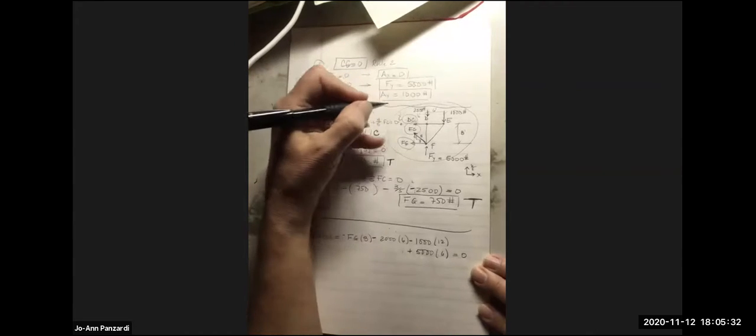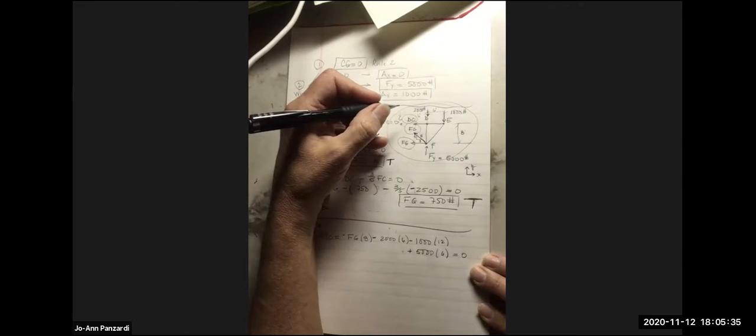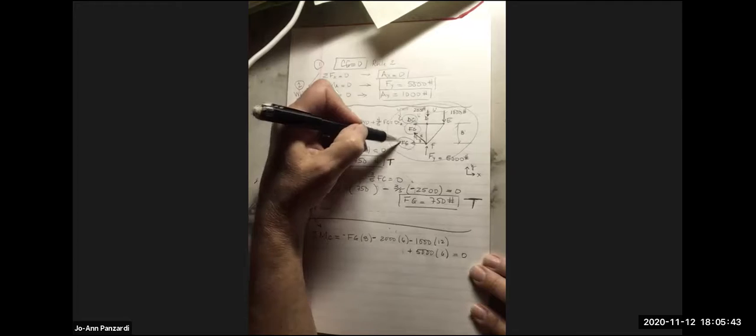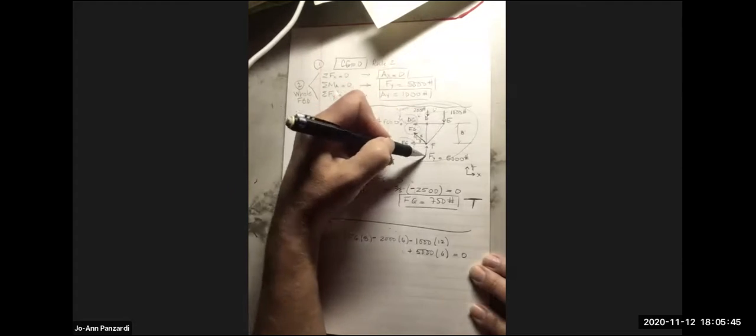And at C, there is a force. What is it? 2,000. But that doesn't create a moment because it's at the point. So it's only FG, the 1,000 force, and FY. And FG again should turn out to be 750 pounds positive with a T. There are many times that you'll use a virtual point because you want to make this the easiest you can, the least amount of work.